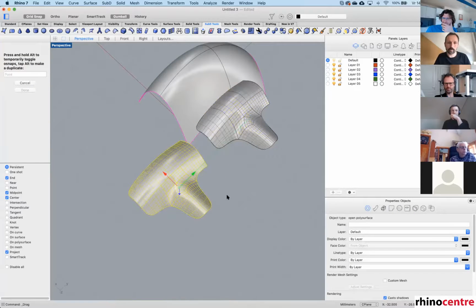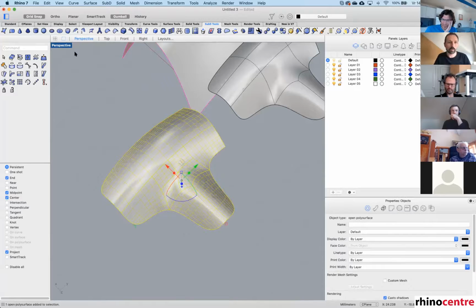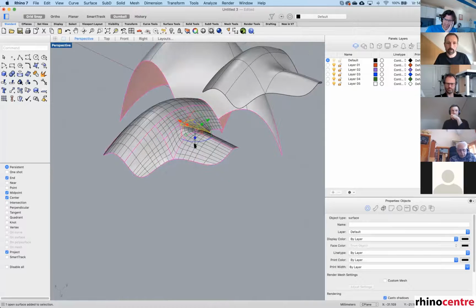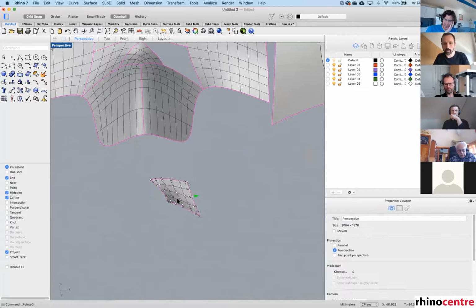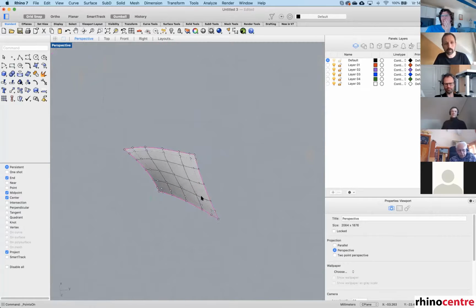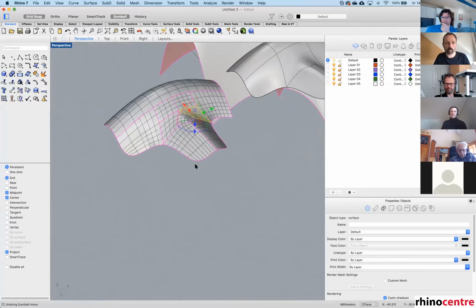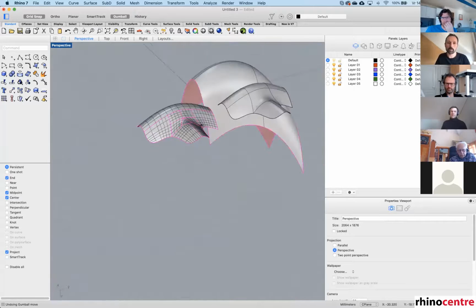The result you get is still a lot of four-sided Nurbs patches. If you explode this, you'll see you have all those singular patches, and these are again just simple Nurbs objects, which are quite complex. And that's something to be aware of when converting back to Nurbs.